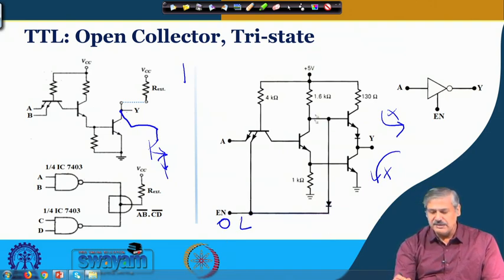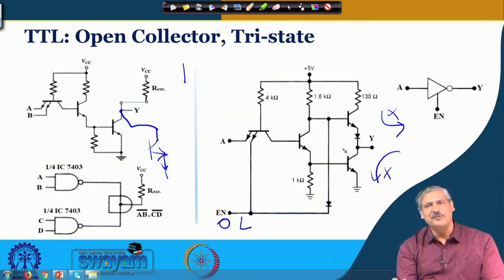In this particular case, you see for any of these cases, this current will be drawn in this direction. So, this transistor will be off. Okay. So, this transistor is off. At that time this can become high as in earlier normal operation, right, but because of this diode which clamps the voltage to 0.7 volt and 0 volt over here, which is not sufficient to make both of them on, this transistor is also off. So, both of them are off.